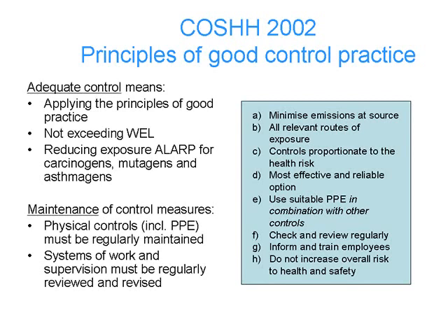COSHH 2002 Principles of Good Control Practice. The COSHH 2002 regulations introduced Principles of Good Practice for the first time as mandatory. It's nothing new, just a rejig of the long-established hierarchy of control. There is a stronger emphasis on control at source, reliance on good design and physical measures rather than procedural controls and PPE as the main ways to reduce exposure. There is also a broader whole task view of controlling exposures, all routes of exposure, and interaction with overall health and safety.